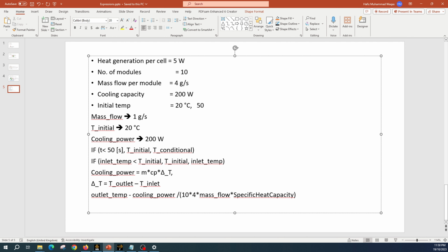Here, let's call it inlet temperature. So here is cooling power. Everything, m Cp, will come into the denominator. So you can see m Cp has come into the denominator. Here is cooling power, and then delta T. So we have just separated inlet and outlet. So Q over m Cp, and the outlet temperature. So here is the delta T.